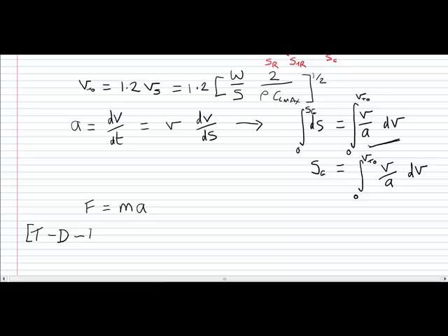And then while we're on the ground, we've got this additional drag term, which is our frictional rolling resistance. So that's our force. You've also been computing an estimated aircraft weight, which you should have at this stage in the project. So obviously to convert that into mass, we need to divide by g. So you've got your takeoff weight estimate, which will divide by g to convert it into a mass, multiplied by a.